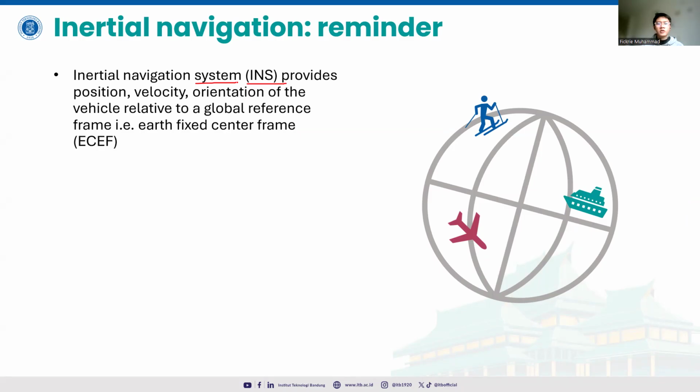The IMU consists of the gyroscope and the accelerometers. It can also use a magnetometer as an additional sensor to compute the heading. As we know, the gyroscope and accelerometers both compute the motions, or the orientations, that later on can be integrated to derive the positions.